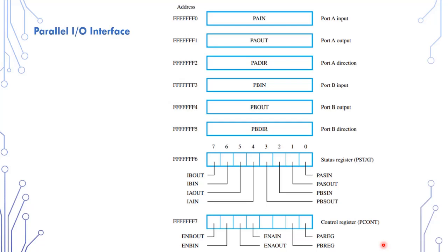Port A has 2 control lines, CA in and CA out, which can be used to provide an automatic signaling mechanism between the interface and the attached device for devices that have this capability. For an input transfer, the device places new data on the port's pins and signifies this action by activating the CA in line for 1 clock cycle.